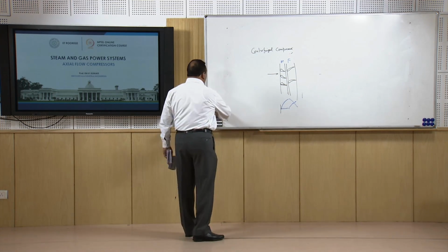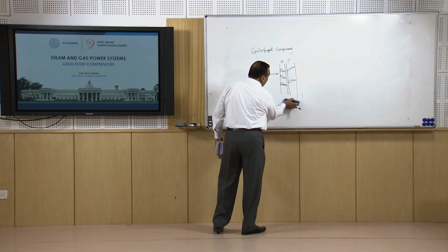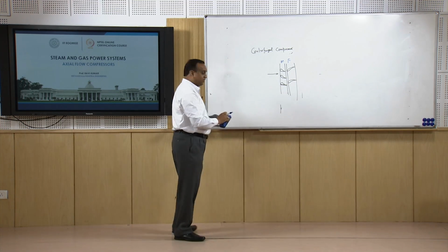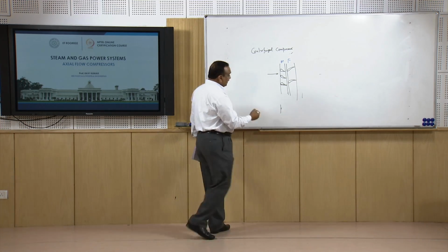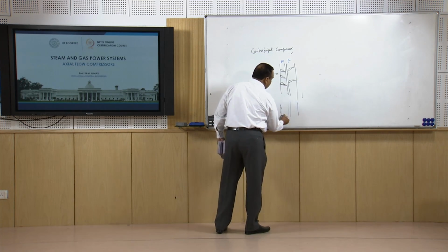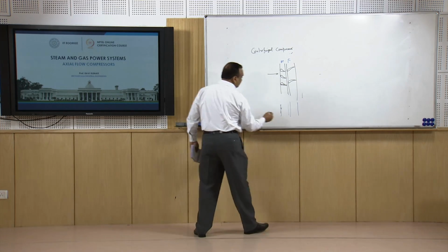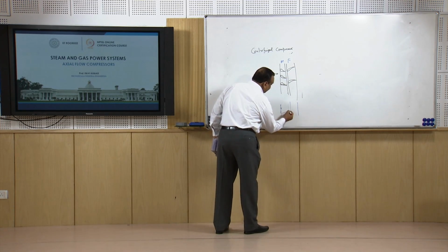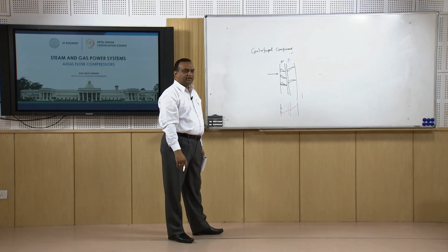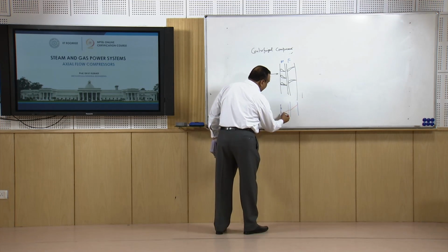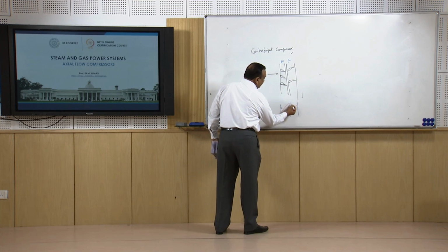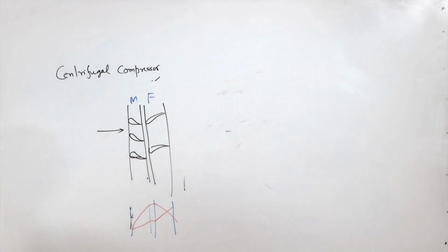But normally the axial flow compressors work as a reverse of the impulse reaction turbine. So, here there is a pressure rise in the moving blades and fixed blades as well. Regarding velocity, it increases in the moving blades and it falls in the fixed blades.